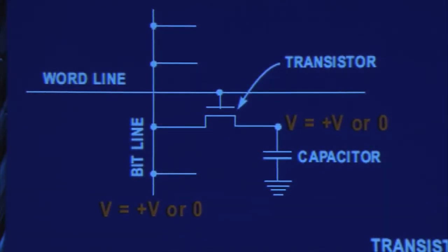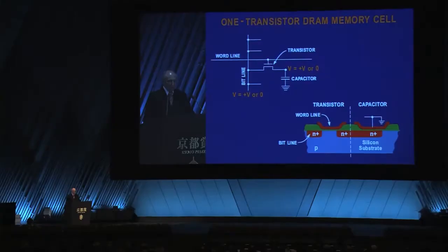In my initial thinking, the capacitor was the gate of another transistor, and reading was accomplished by monitoring the current flow in that second transistor. I was very excited about this idea, but it wasn't as good as I wanted. It required multiple access lines with complicated drive schemes, or an additional transistor to make a memory array function properly.